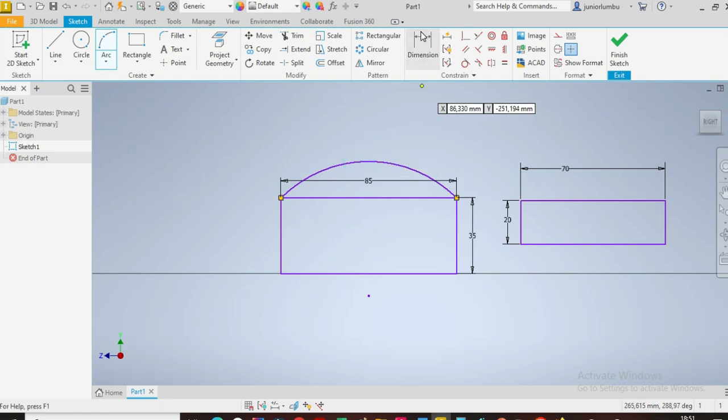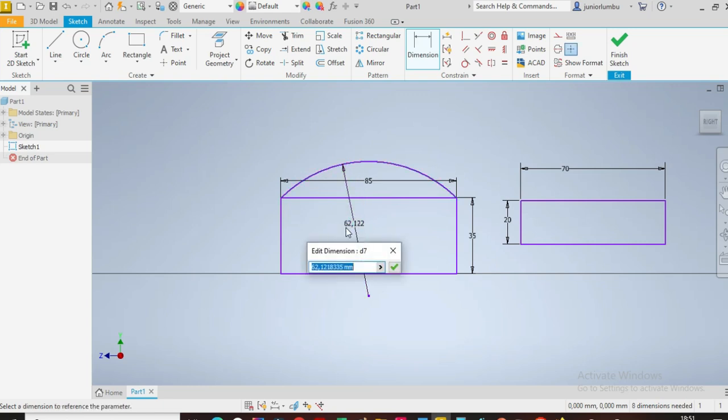All right, same way I can also give dimension if I want. So in this case, I'm going to restart. I come there, I click there, then I need to give the radius. For me to activate this, I need to left click on my mouse, then I write in the radius that I want. I say 65 millimeters. Then I have a 65 millimeter radius there.